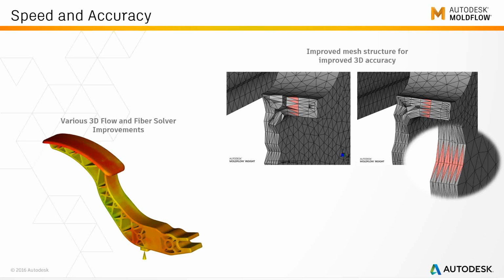We will see a little bit of an increase in the element count as a result of this. At the same time, though, the structure is a little bit more efficient as well, so we don't necessarily see as many dense patches of TET elements appearing, and the meshing itself is actually a lot quicker too, about 20 to 30% quicker this year for creating TETs.